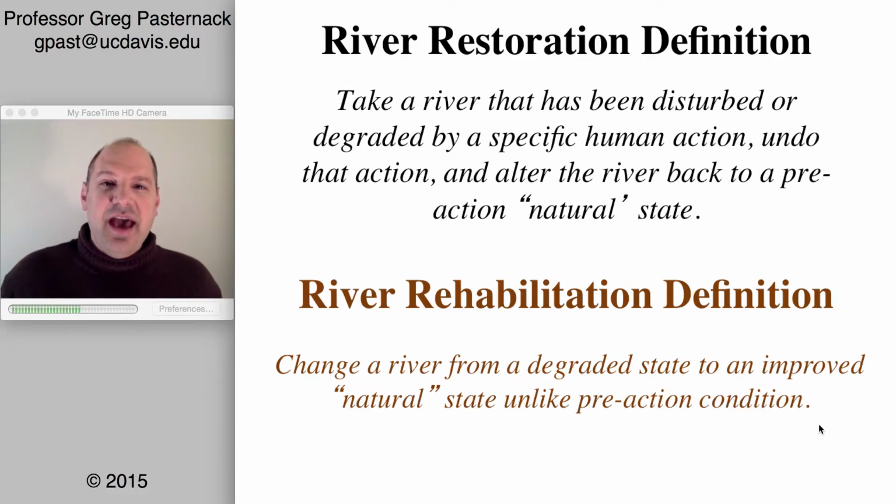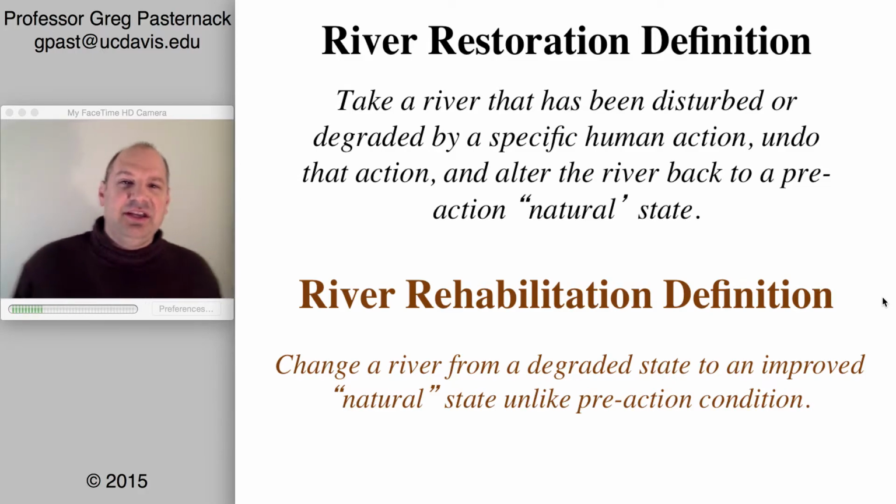And as a result of that, there is another concept or definition, river rehabilitation, which is also a going backwards idea, but one in which we're not going to go all the way back. We're going to try to improve it, get to an improved natural state, and it isn't necessarily going to be the pre-action condition, but it's going to be something better than what it is.